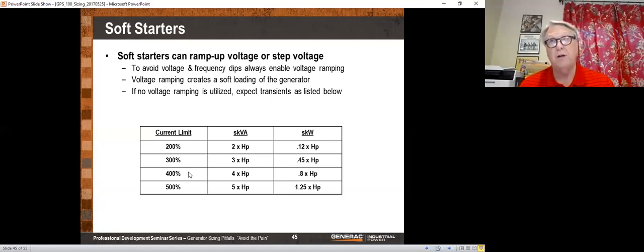and you choose soft start, it will put in a soft start without a voltage ramp. It's called a step start. The reason for that is there are manufacturers out there that produce elevator controllers that are soft starters but do not have the voltage ramp. And that's a terrible thing. They're terrible to try to start on a generator, but we're trying to take care of you, so that will be the default in the program.